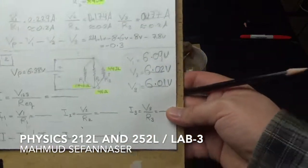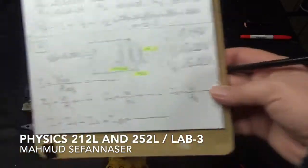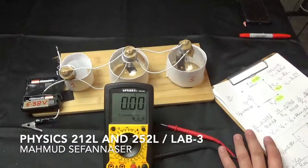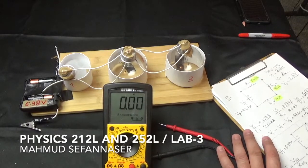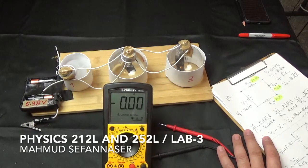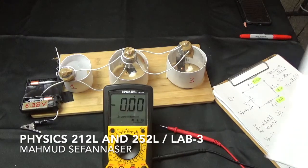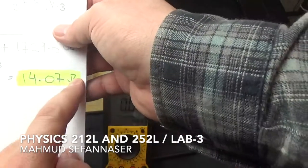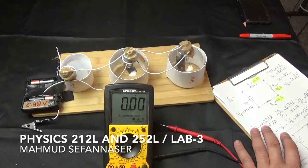So we will try to calculate I first, which is the current that flows in this circuit. It should be 6.02, let's choose 6.02, divided by our equivalent. And our equivalent for these resistors is 14.07 ohm.